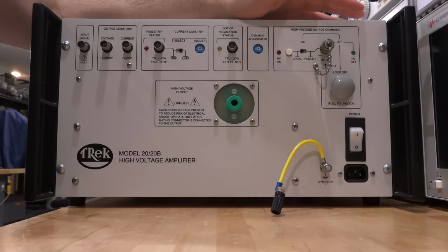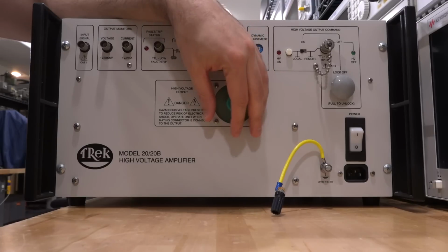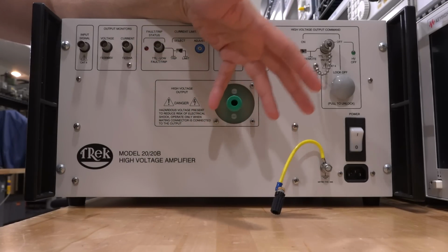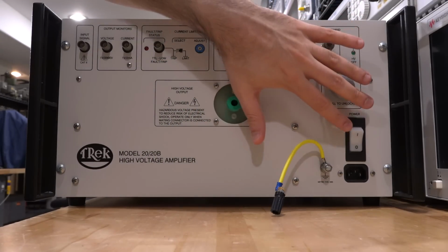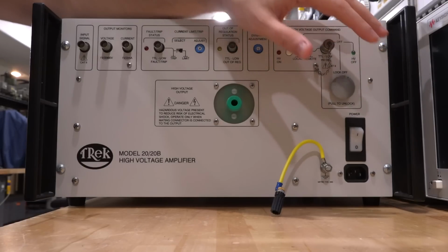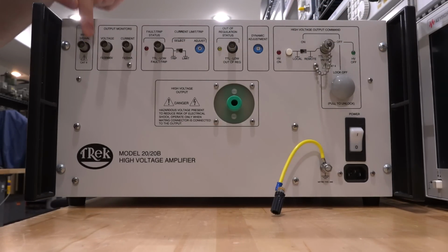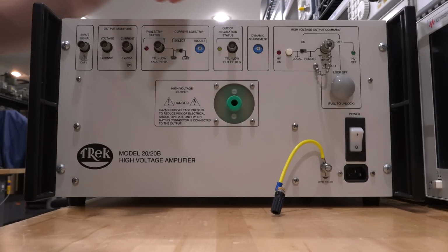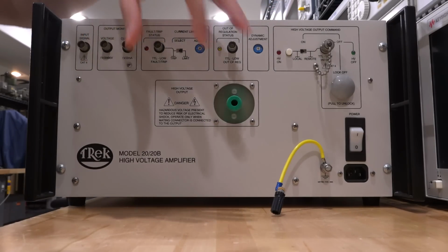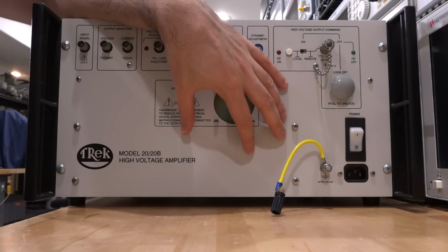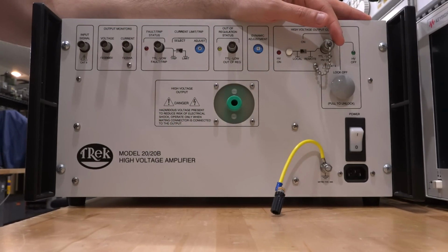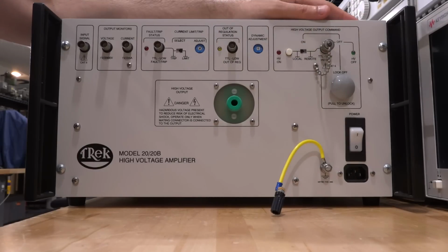I can tell you that this is very dangerous. I made a simple mistake with it while I was trying to measure something. I had the output connected to some resistors. I was trying to make a measurement around 100 volts. The output power supply was enabled, and I accidentally plugged into this the multimeter ohms measurement. And of course, when you want to measure the ohms, you have to apply voltage in here, and this instrument doesn't care. So as soon as I plugged in the ohm meter in here, several thousands or tens of thousands of volts appeared here, and it vaporized everything that was connected to it. So it's very dangerous, and perhaps the interlock is one way to avoid mistakes like that.